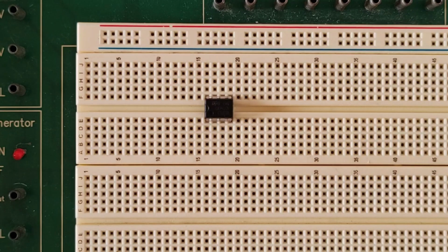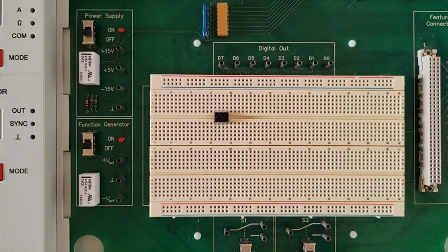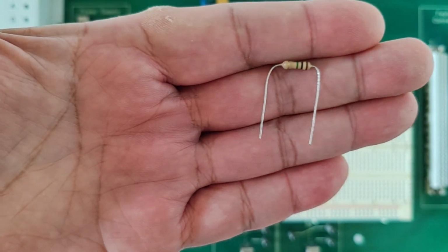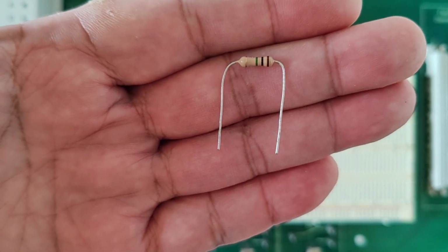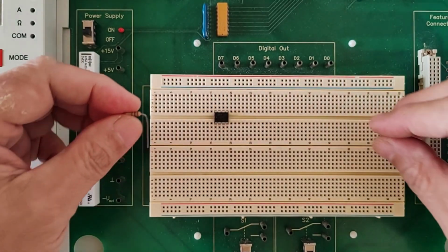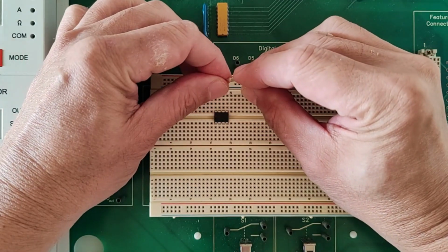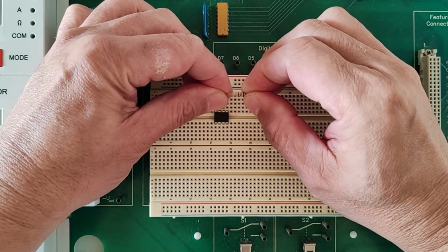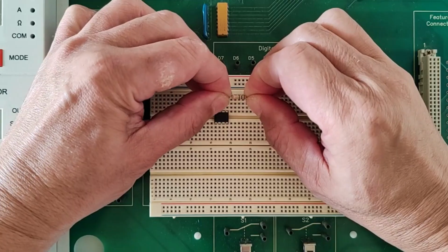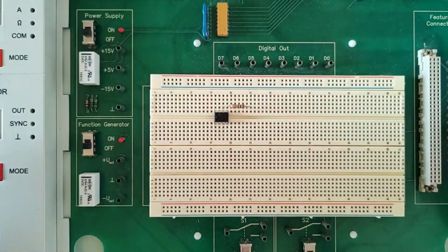Okay? Now, let us connect the other components you'll be needing on the circuit. For instance, on pin number 6, the output, we need a 1 megaohm resistor, which I have here. How do I know? Again, color code. The 1 megaohm resistor is connected in this manner: one of the legs goes on pin number 6, like so. Just connect it like that. Pin number 6, there.